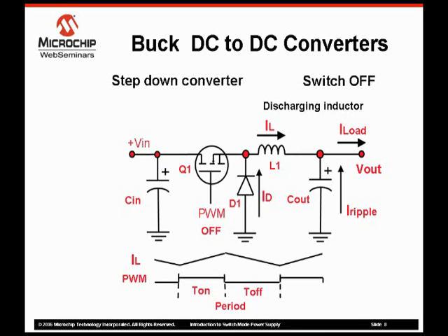The choice of the inductor value relative to the PWM frequency is important. The larger inductor value L1 makes L1 physically larger and heavier, but it will reduce the current ripple that flows into and out of the capacitor, reducing the resultant ripple voltage and reducing the heat dissipation of the output capacitor.